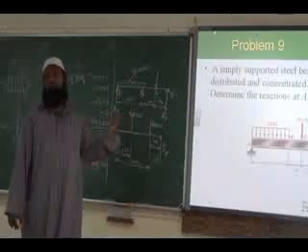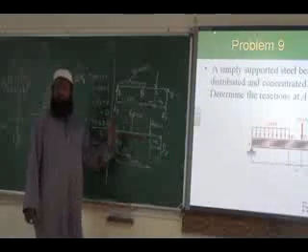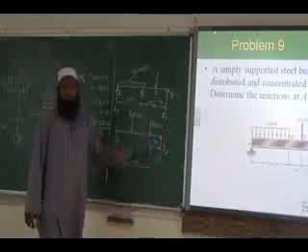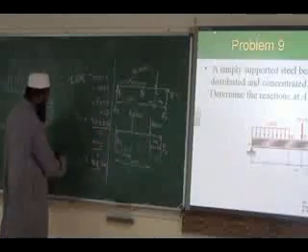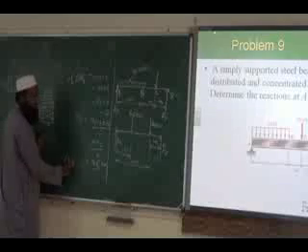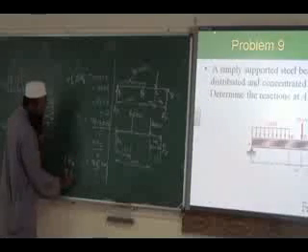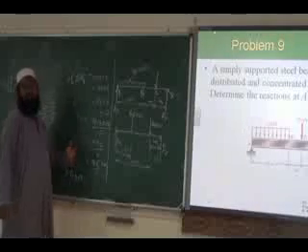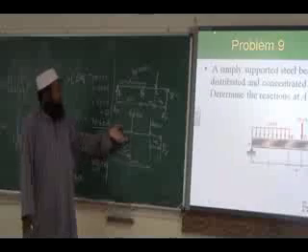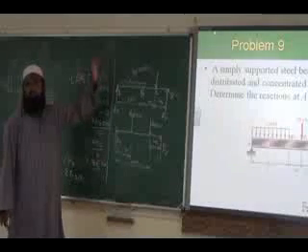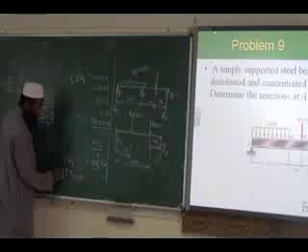Now you have to find out Ay. For finding Ay, you can follow the same procedure. You can take moment about D, instead of taking moment about A, sigma M. Or the other procedure is you can consider sigma Fy equals 0. So consider all the vertical forces, say upward forces are negative and downward forces are positive. I take this sign convention.